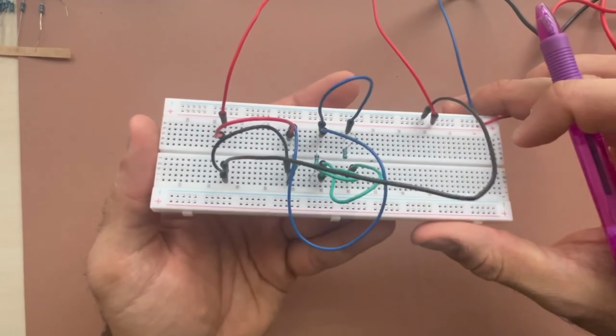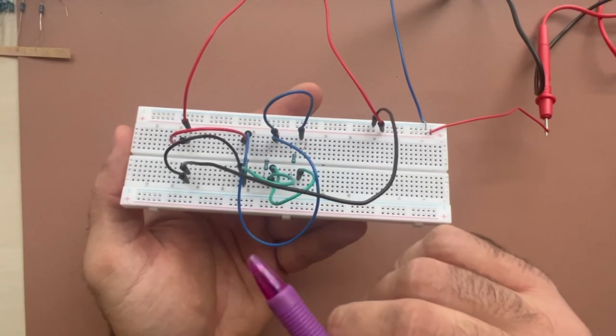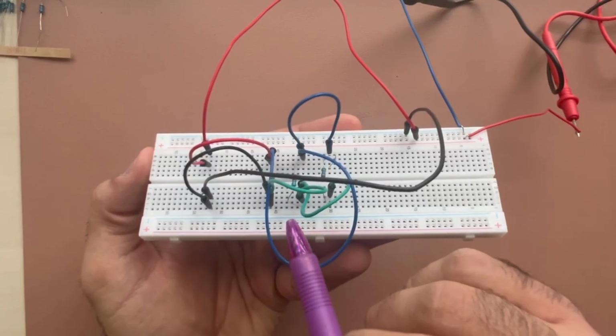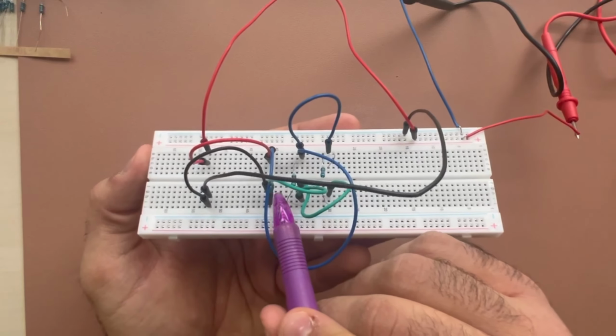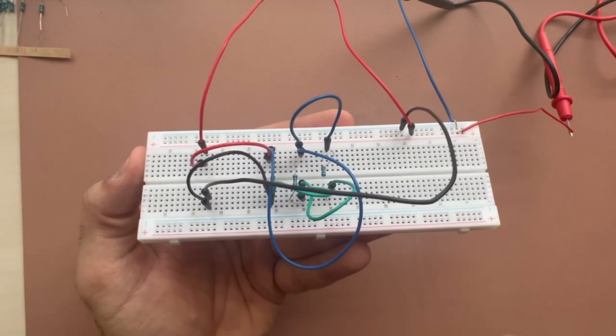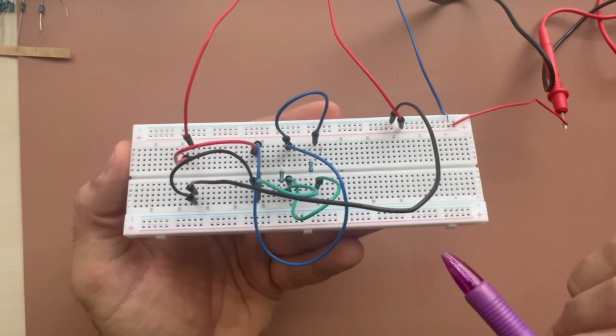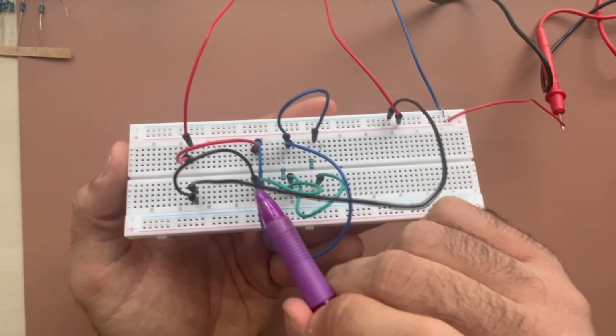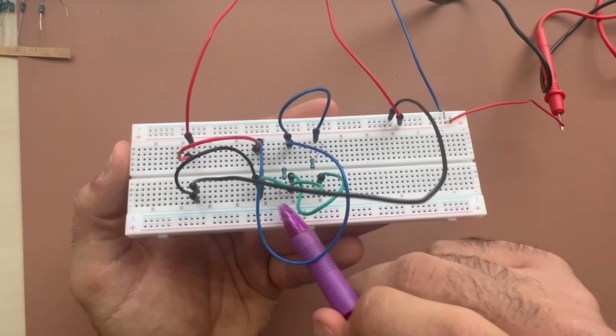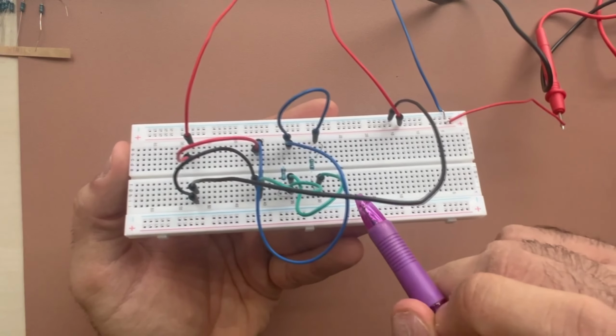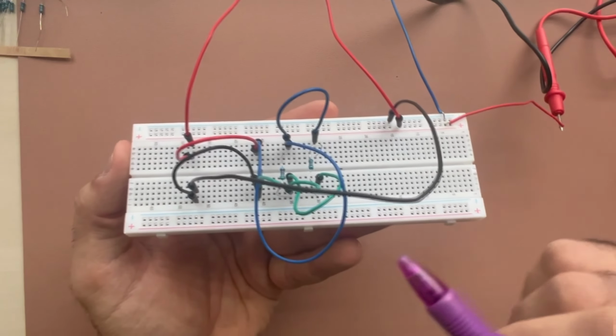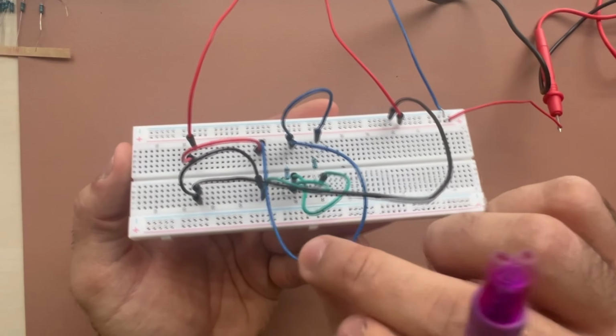So let's talk about the main circuit. As the question asks, for the main circuit, I have 3 resistors in parallel. One resistor, on the left side, I know as 2K, another one 5.1K, and finally I use 10K. Right now, we know that each of these spots are not connected to each other, but for a parallel circuit, I need 2 common spots. What can I do? I can use the jumper.